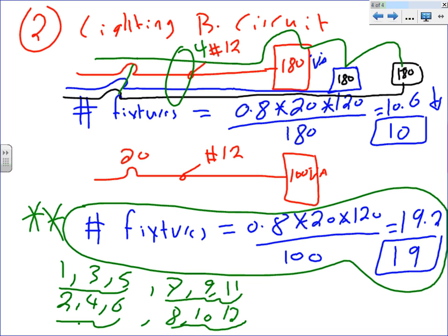As long as it's a lighting related circuit, that's a cheaper way of doing it. But remember, you are going to be using your conduits for the receptacles also, not just the lights. If you design your conduit system right, you can utilize the same conduits to pick up your receptacle load and your lighting loads, and you might be able to pick up some small equipment load.